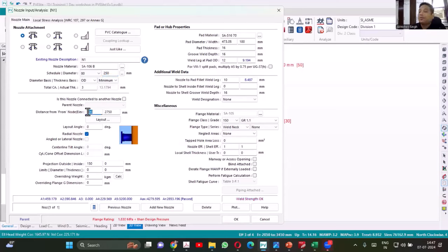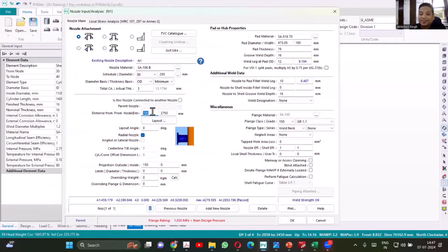Now where do you want to put that nozzle? We'll be coming to RF pad also, don't worry. I'll go like this and then we'll cover the RF pad. So for distance, right now we don't have the elevation known, so we can go with any dimensions. It's a 10-inch nozzle, so you have to keep the center away. Let us take 500. If elevation is given, I can directly add it here. That will be taken from the base level where we have kept elevation as 0, 0.